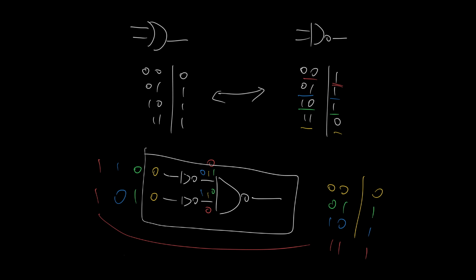So this will give me an exclusive OR gate. Now all that remains is to replace each of these gates here with NAND gates. So we know that inverters are made by just fusing together the two inputs of the NAND gate. So I've got, let me change colours, this part of the circuit here is given by this part of the circuit here. And similarly for the lower part, I've got this and this.